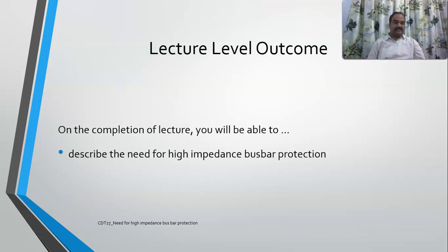In today's class, we will go through a simple mechanism to overcome this problem of saturated CT and this false operation for external faults. There is a scheme used in power systems called high impedance busbar protection, which is generally used to counter this problem of saturation of CTs.